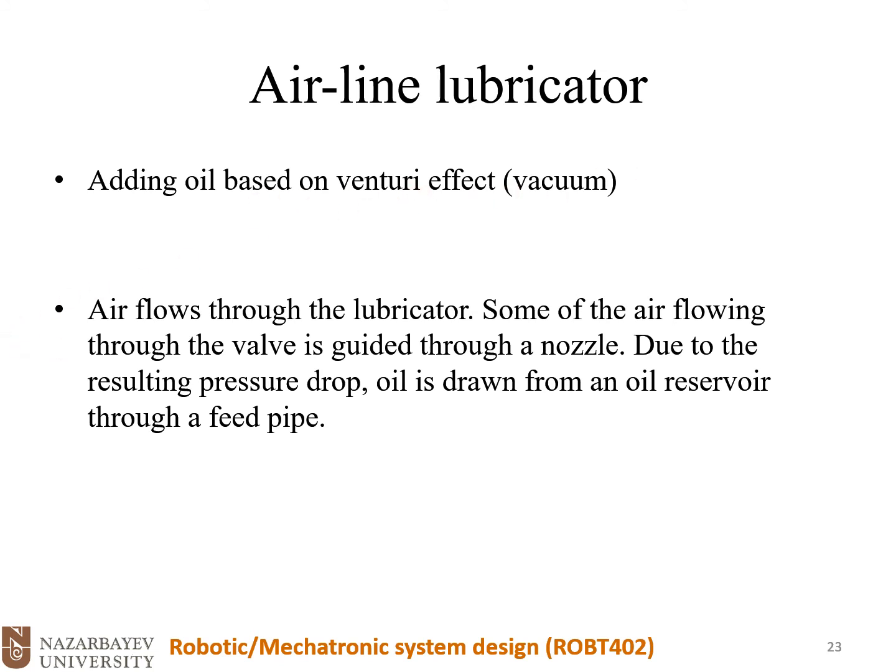Air flows through the lubricator. Some of the air flowing through the valve is guided through a nozzle. Due to the resulting pressure drop, oil is drawn from an oil reservoir through a feed pipe. Okay, I will explain it in the picture.